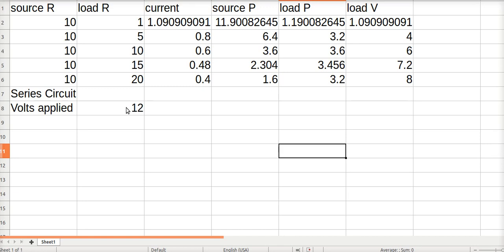Where this comes into play, however, is the radio in your car. You want the biggest sound in your speakers, or if you have any kind of system where you are trying to get volume out, what you have to do is match your speaker impedance with your source impedance.